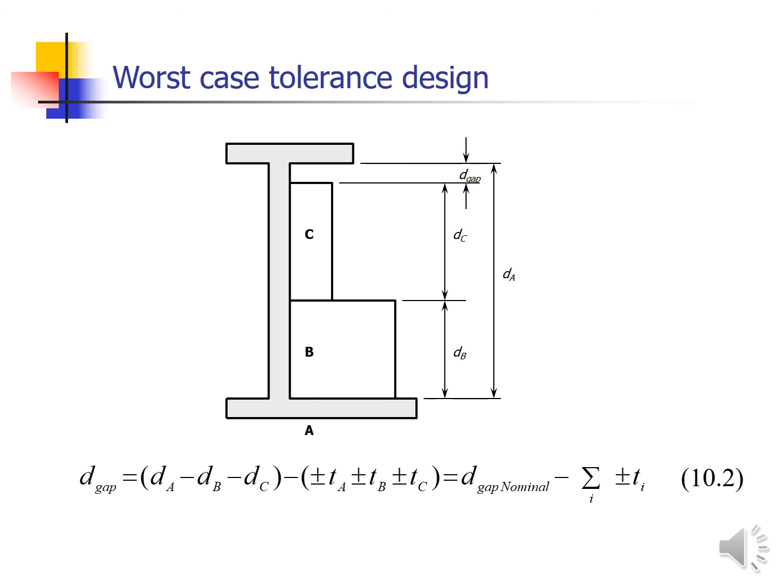Okay, but when you set the tolerance, for example 10 mm plus minus 0.001, this means 1 micron. Okay, we need a more precise, capable machine to create this part.